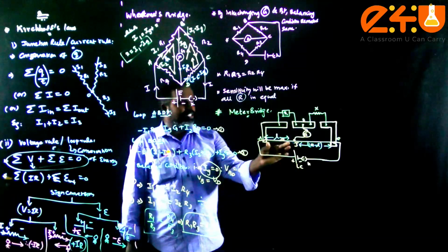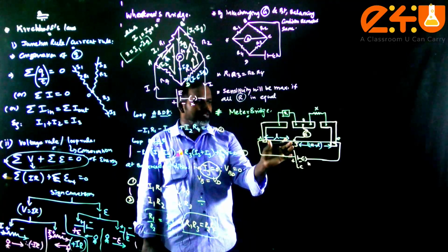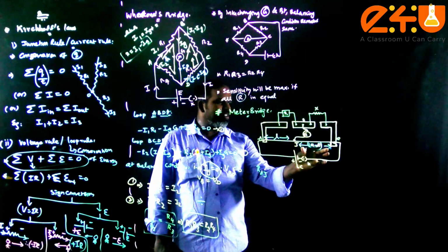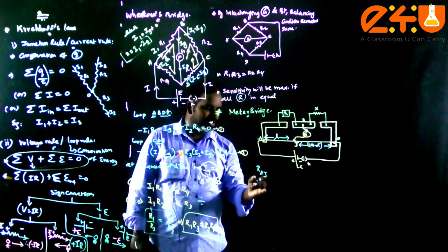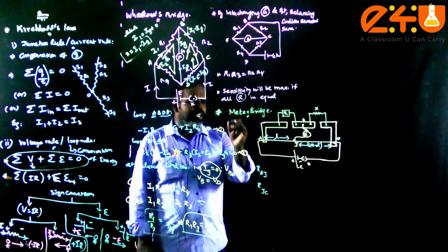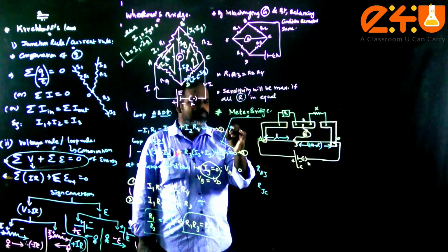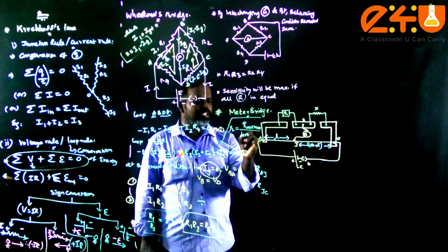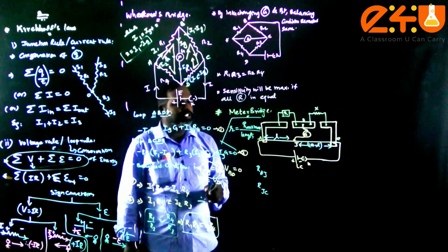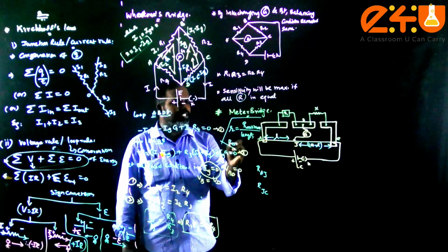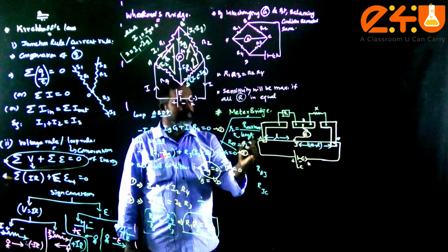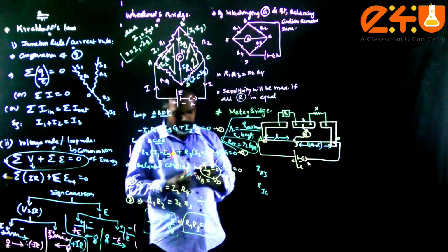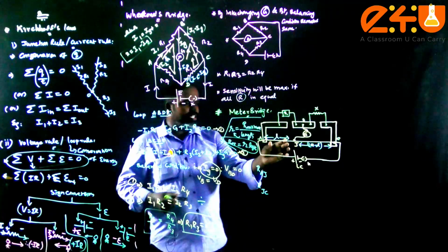Okay. So the resistance offered by the portion of the wire AJ is taken to be RAJ. The resistance offered by the portion of the wire JC is taken to be RJC. Here I am going to define a small term, small r, that is resistance per unit length. So this is the small r definition. From this I can write that resistance is equal to small r into the length of the portion. Small r into what, students? Length of the portion.